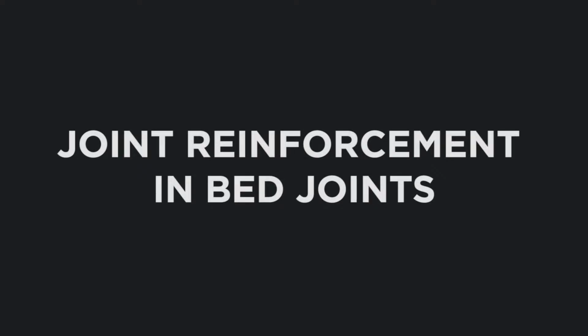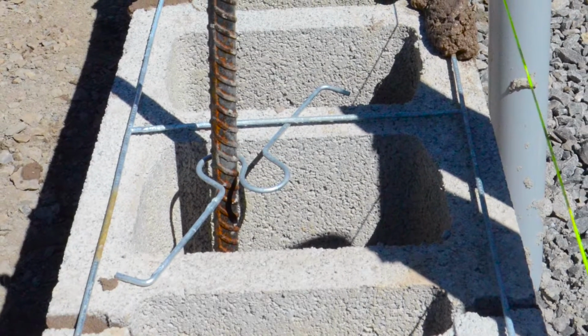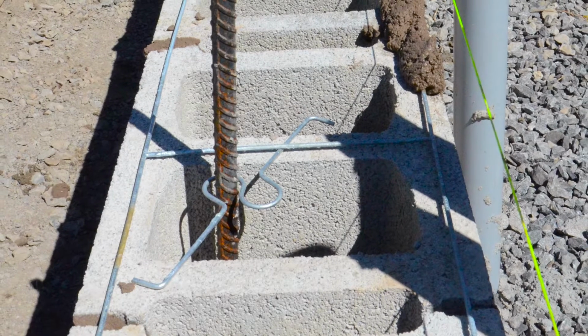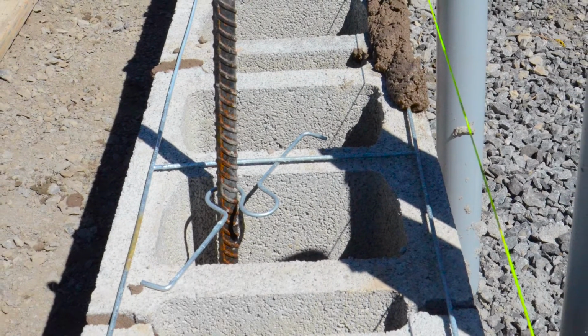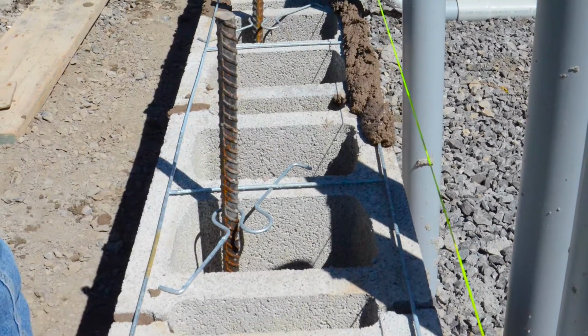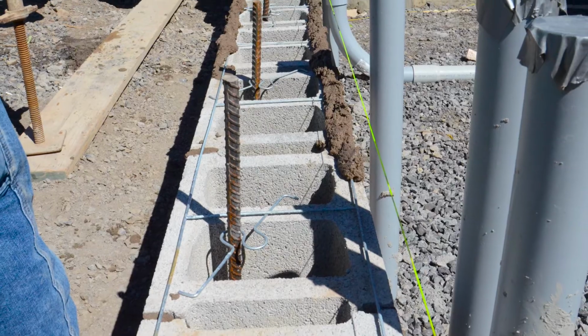Joint reinforcement in bed joints. It is generally acceptable to lay joint reinforcement directly on top of the masonry course. Mortar is then spread over the wire and face shell or unit in one operation. Due to irregularities in the masonry and the wire, mortar surrounds the wire and bonds the components of the assemblage.